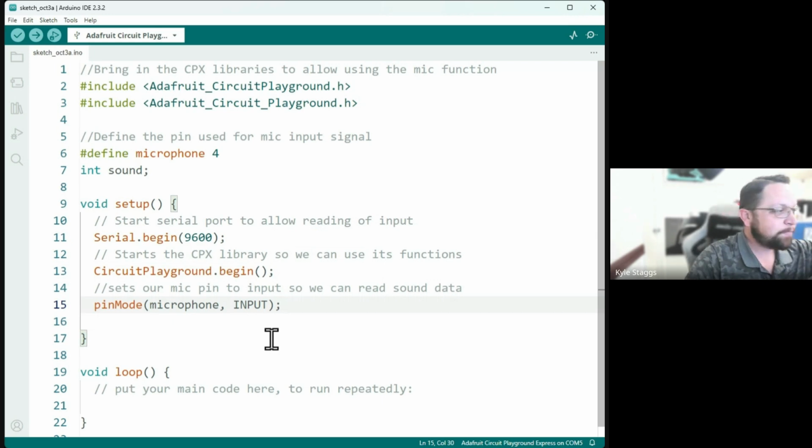In code, there are some things we have to do because they are axiomatic to actually doing I/O programming. Pin mode we need to use in order to make sure we know we're using this pin as input so that the pin is not assigned to some other gibberish in memory or assigned to output or doing something strange.